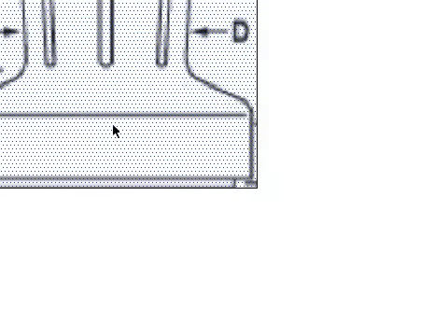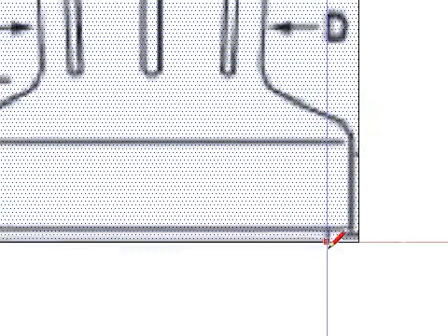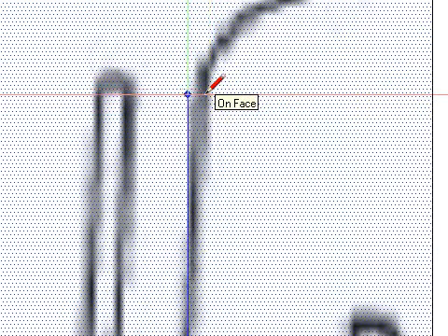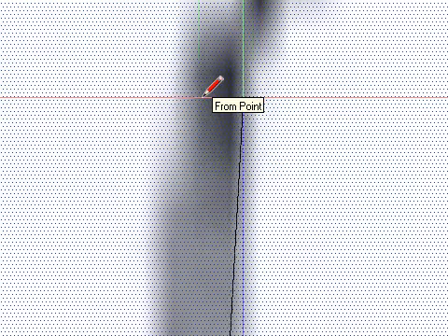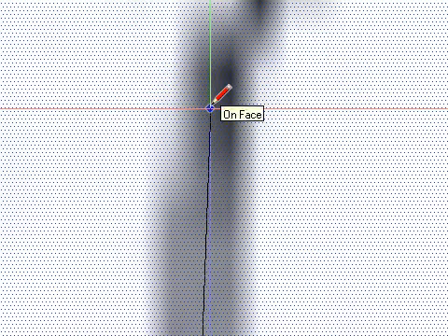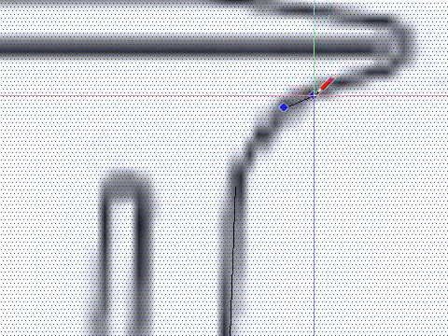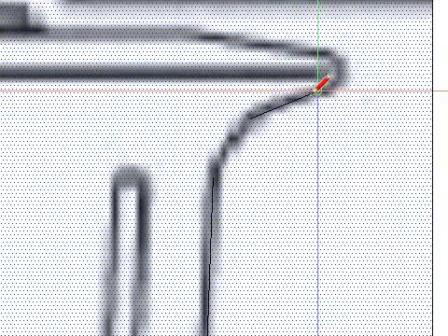Now what I want to do is trace the outline of half of the winch to get a cross section of it. So I'm going to start here, go there, there, there, and I'm going to do the arcs later. Then hit escape to get out of the line, so leave the space for the arc. Sometimes you have to zoom in to get SketchUp to allow you to place a point where you want, otherwise the inference engine tends to line it up with the rectangle.